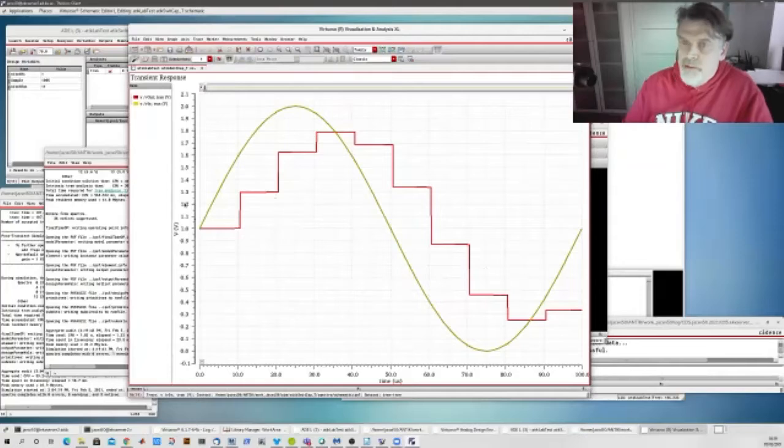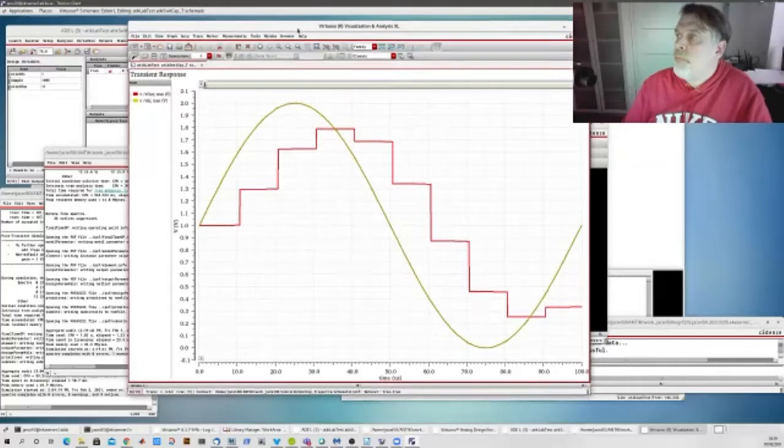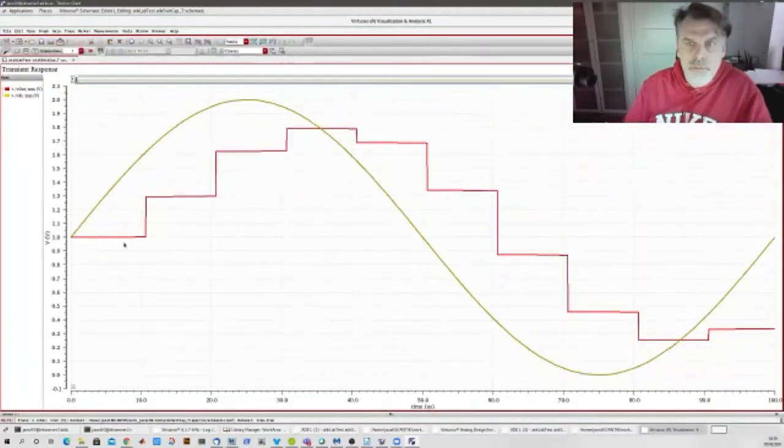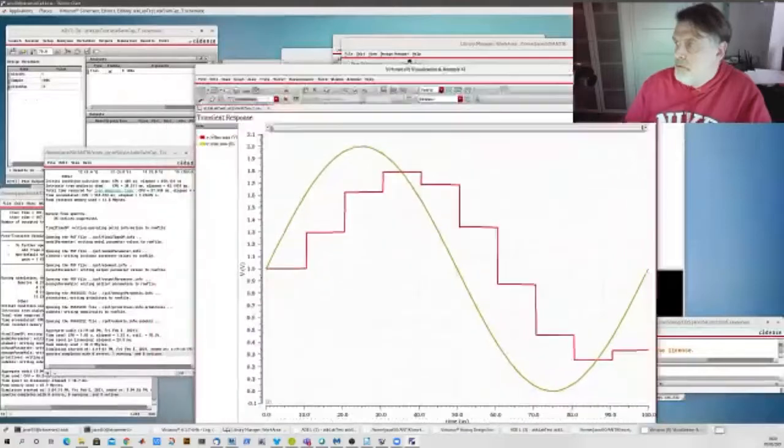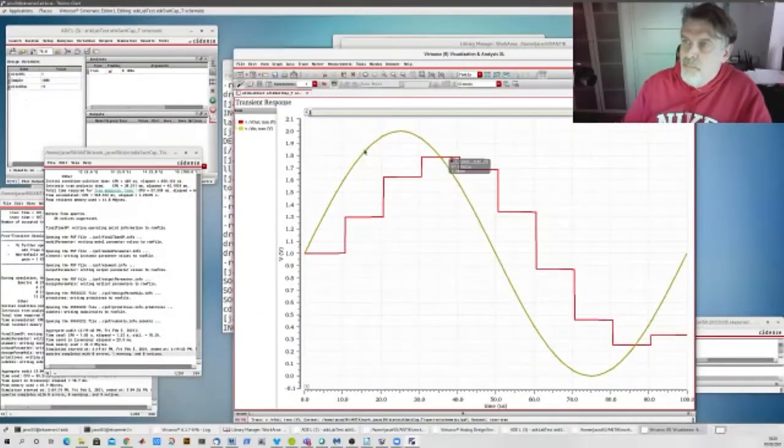Right, so here we see the effect. Now we notice that my original signal, the yellow one, which might be hard to see on the video, is my original input signal. And then I had a case where I have a phase shift, as I would expect in a low pass filter. So I would not only attenuate the signal, I would also phase shift it, which we can quite clearly see here. The number of degrees, one could argue, maybe 20 degrees or something phase shift here. We also see that there is an attenuation of the amplitude.